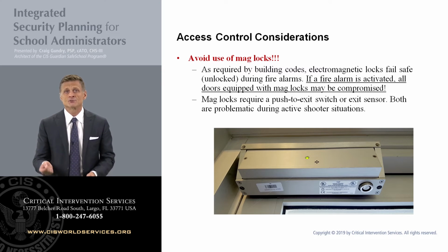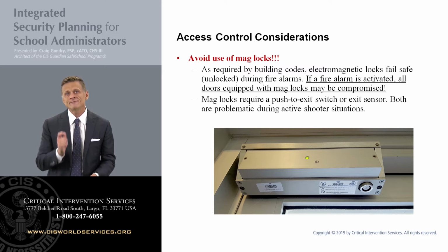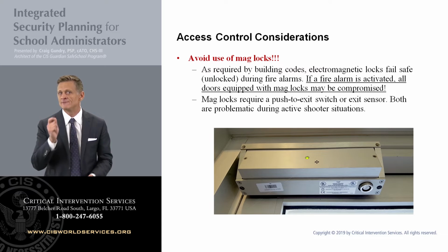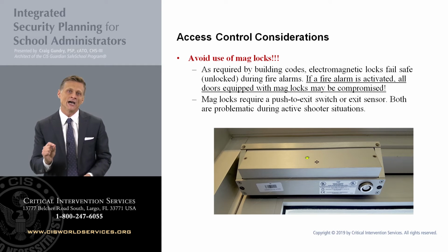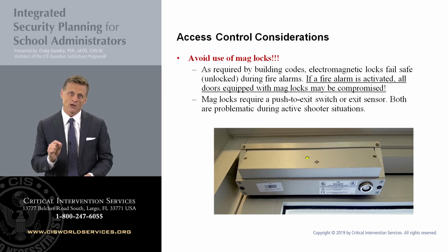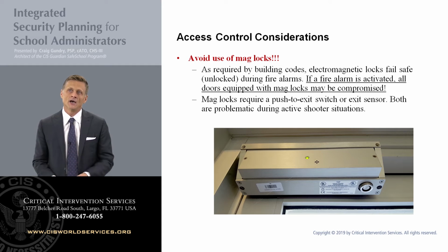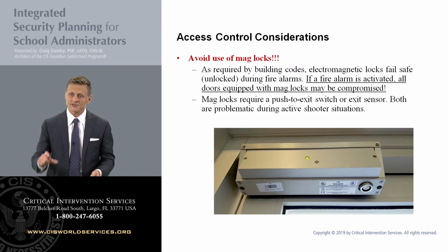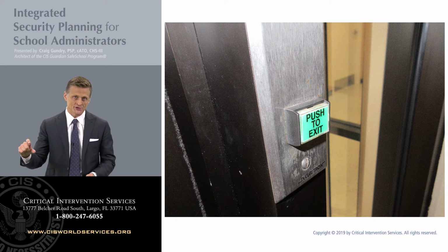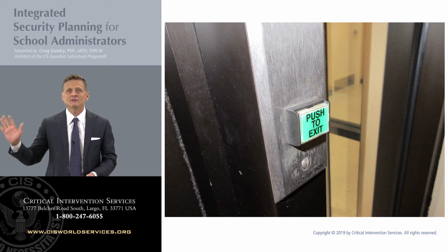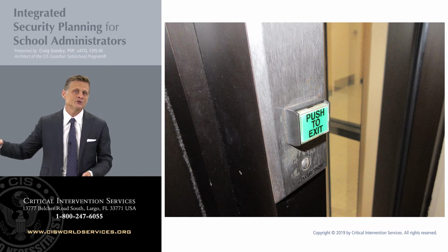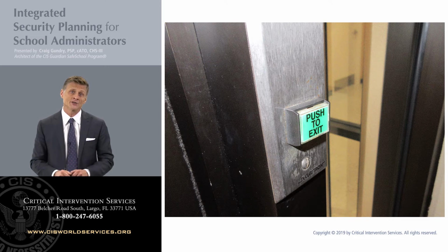As far as the exit sensors, my team has actually tested exit sensors in a number of different building installation applications over the past several years. And quite frequently, if somebody runs at that exit sensor very quickly, they don't always reliably disengage. That's a big problem. The second, with the push-to-exit switch, quite often we find in the real world these small, tiny little push-to-exit switches that are maybe about 2 inches by 2 inches, green in color, and they are mounted probably maybe a yard to maybe several yards away from the actual egress door.